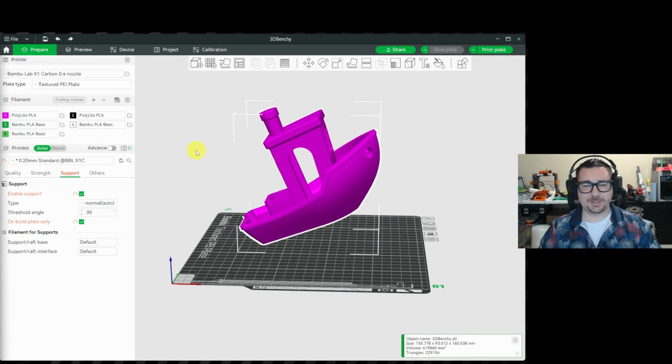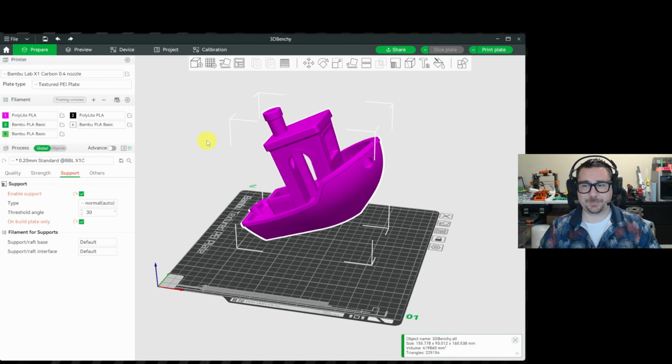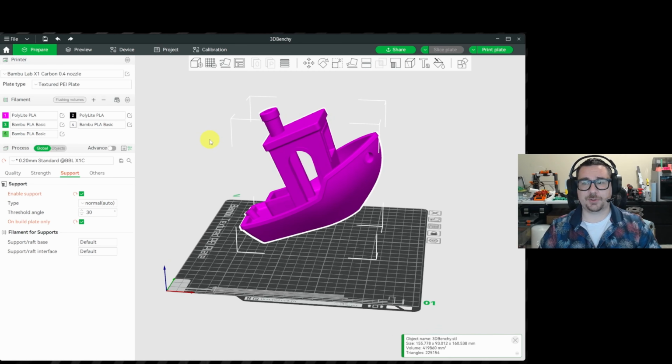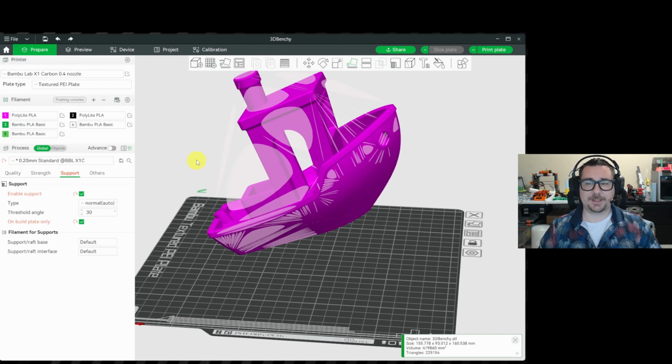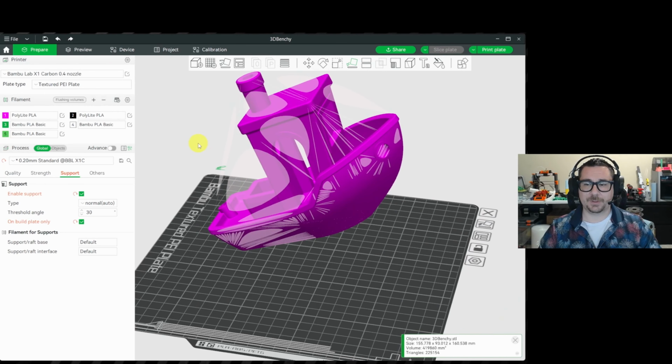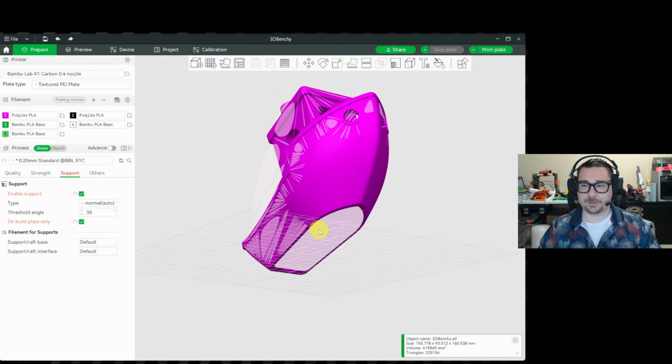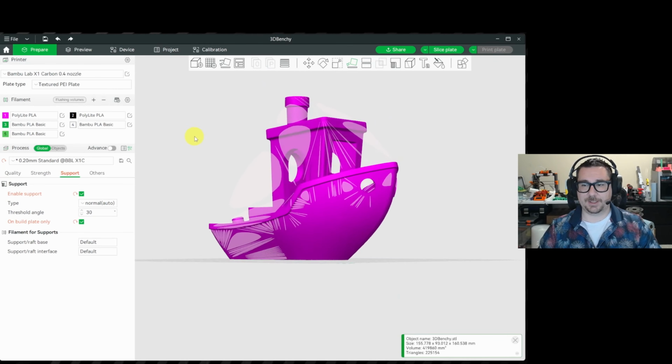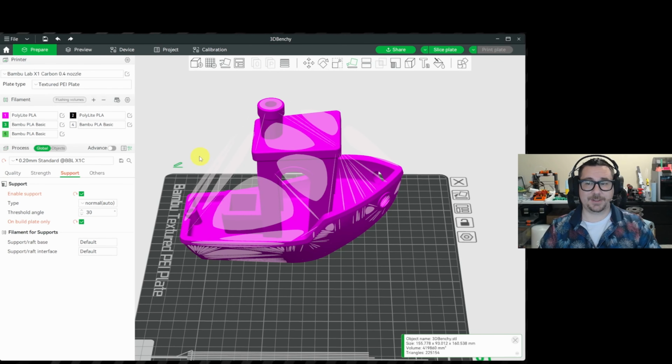Alright, this video is getting a little long, but one last thing I wanted to leave you with is how to place an object on a flat surface and how to cut an object if it's too big. So next to the Move, Rotate, and Scale button is Place or Lay on Face. If you click this, it'll try and analyze the model for good faces in order to lay the part on. Now, us as humans know that the flatter the better, and you can just click that and it will lay it on the face.